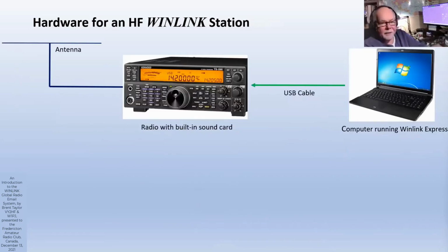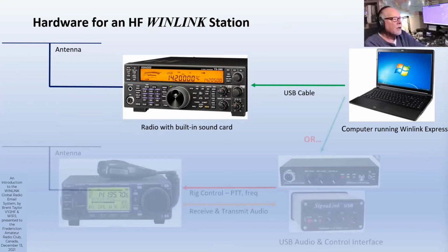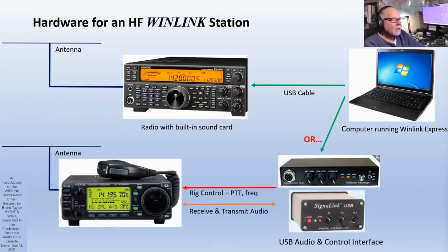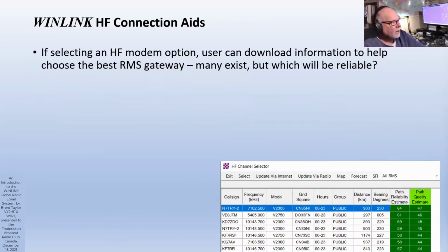If it's on HF, it's not a whole lot different. You've got a laptop or a regular desktop computer connected either to your radio, which will be sporting an internal sound card that you can leverage, or you will use a RigBlaster or a SignaLink or a TNC type thing to control or to talk to the rig that way. And in both cases, the radios are connected to HF, and away it goes.